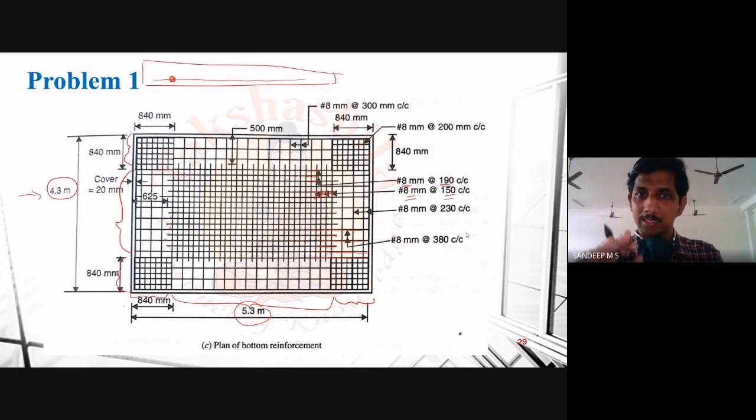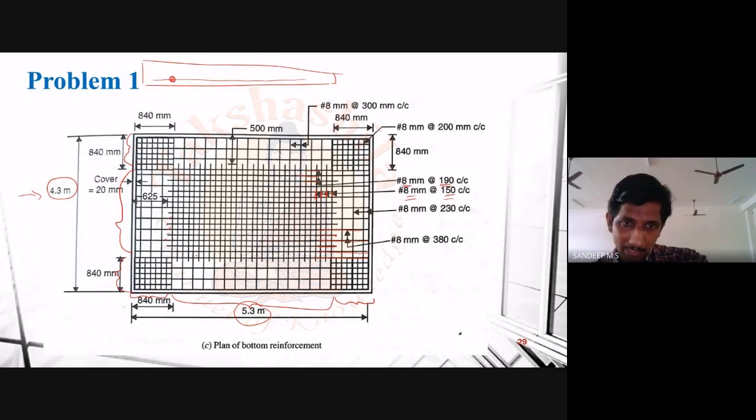So that is one thing. That is the reinforcement, how to provide the reinforcement we designed based on design for middle strip. Now we have one more thing. That is our edge strips. That is 0.12% of that thing. So if you are again talking in terms of Ly, these were actually reinforcement we have designed for middle strips.